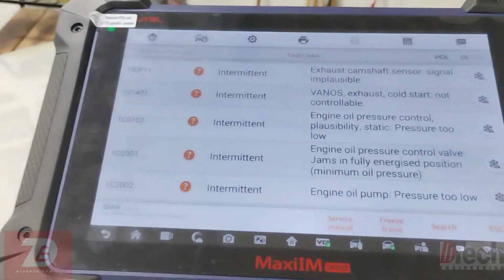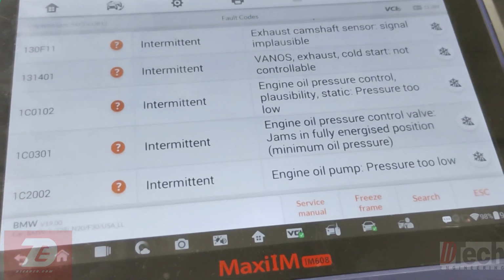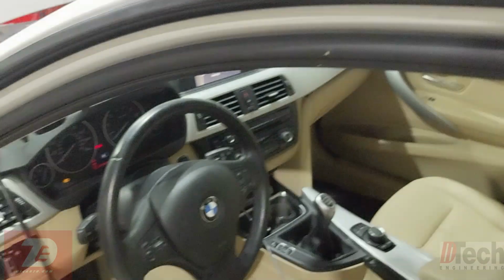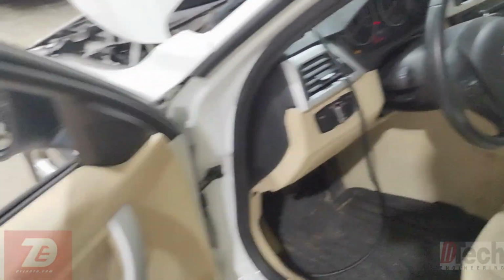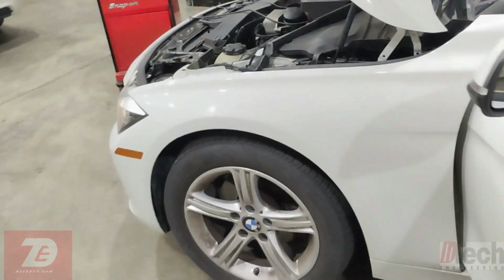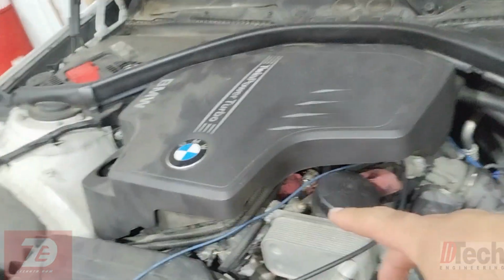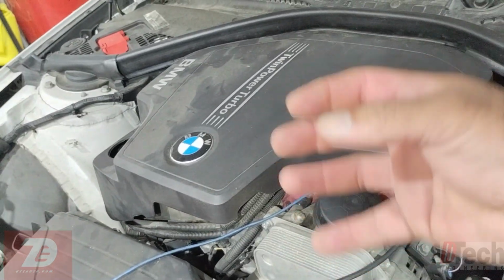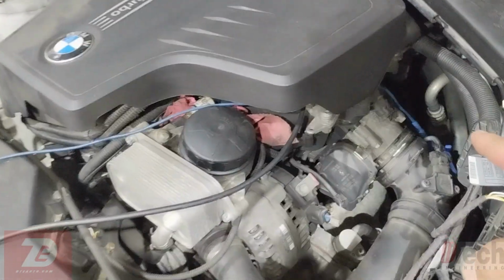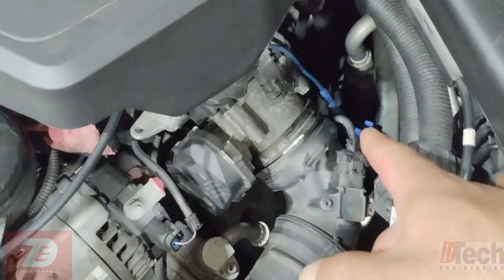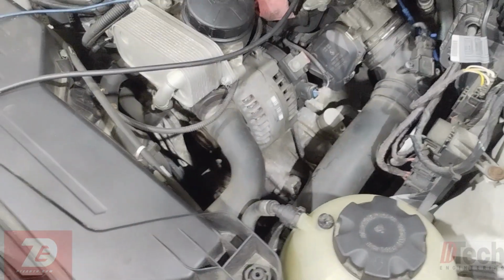But we know that trouble code is not caused by a valve, because we've replaced the valve. So what I want to watch is tap into my oil pressure monitoring, standalone-ish off of the car, and watch the duty control of that solenoid valve.